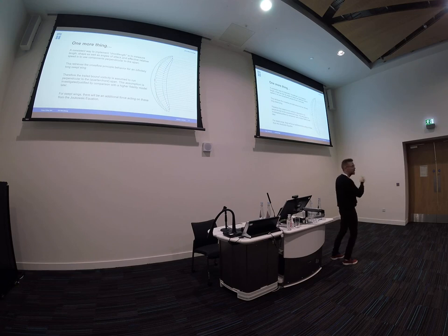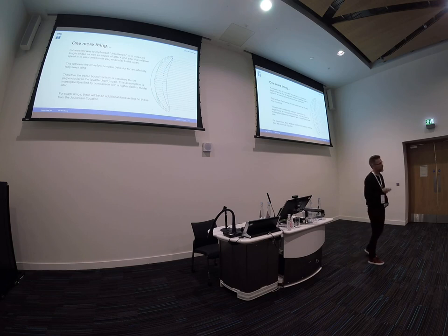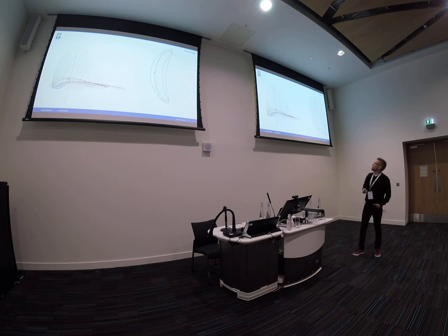So this is the new thing in this way of looking at it, along with the explanation of 3D minus 2D. So these forces, the forces that act on these straight bound vorticity, you can see them here. It's maybe a little bit tricky. You're looking from the wing, it's like half from behind. So the green things are the forces that act on this part of the bound vortex. The blue things are the forces that act on the other part of the vortex. So there's an extra contribution to the forces if you think of it like this.